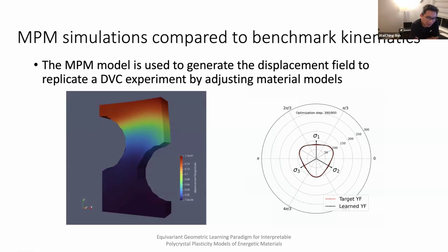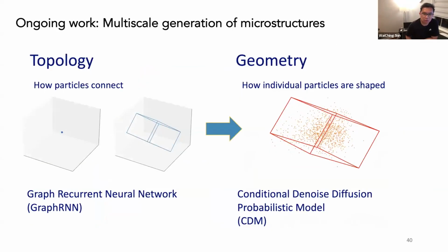And for that, of course, we need to construct an inverse problem that isn't too sensitive to the meshing technique. As you know, if you do material discovery before, different meshes may give you a different shear modulus or bulk modulus, etc. And what we hope is that the neural network approach, if it's trained successfully, can bypass some of the dependence on the mesh and help us recover the constitutive law.